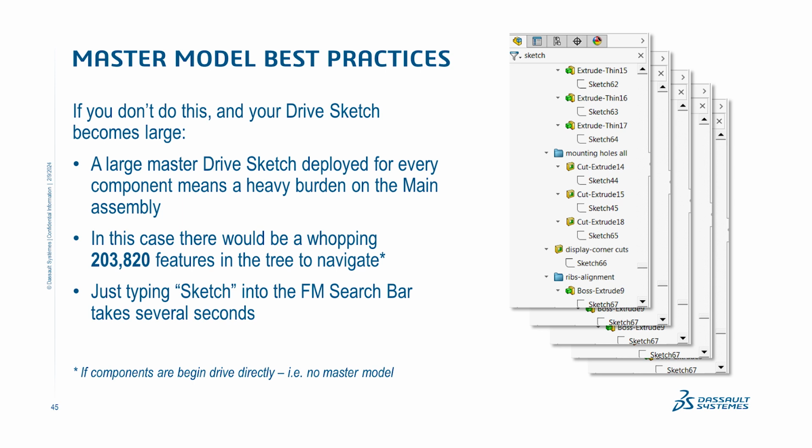And if the master sketch gets too big, you can get hundreds, if not thousands or tens of thousands of features in your assembly feature manager. It could be that you can't even really expand your feature manager because it takes so long to refresh all of those features. So just be aware of that.